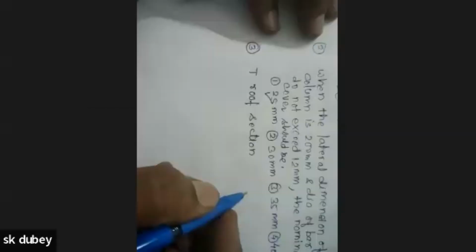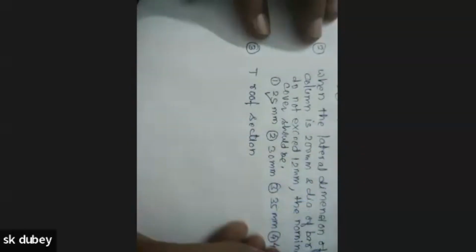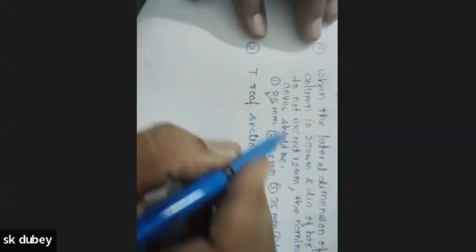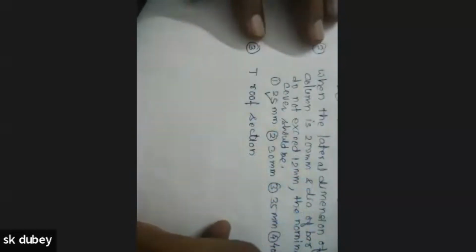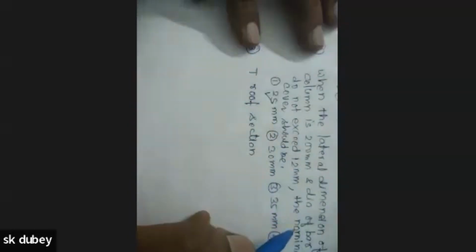So as per that condition, if they had asked the question like that and given the options like that, then we have to choose from them. They had mentioned that it is less than 200, or 200 or less, then also it is 25 mm, for one of the least lateral dimensions. But in GATE, it has been asked in the same language I had used. That is okay, what you are telling is correct. But here it is 25 mm. It is clearly mentioned in our IS code. We have to strictly follow IS 456:2000. Okay, sir.